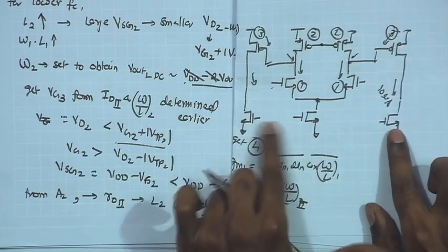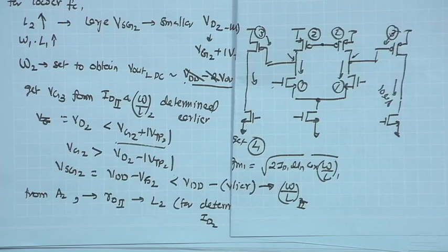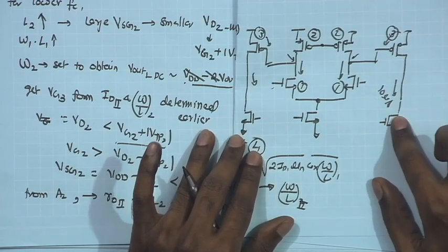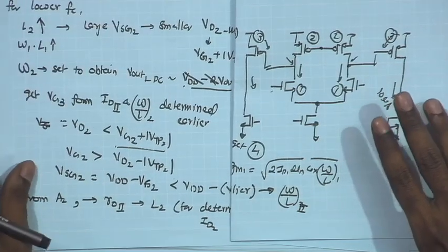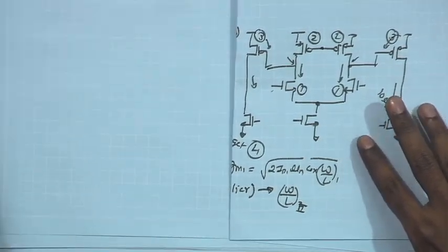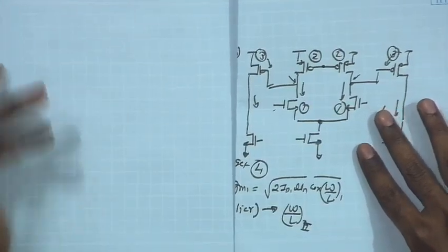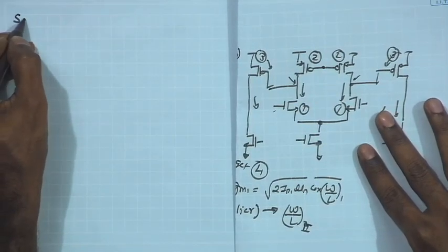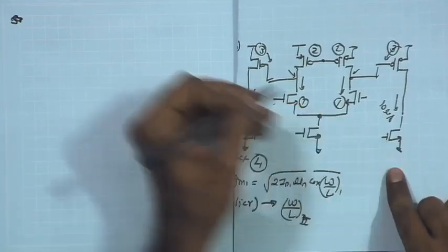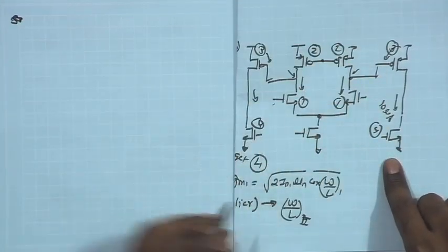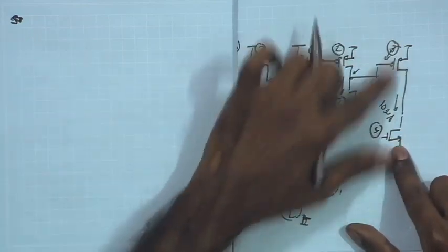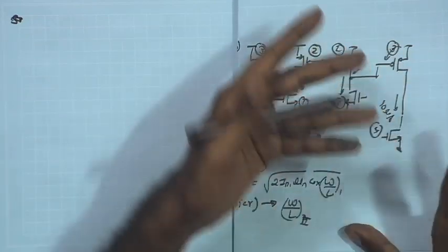Now, the next is the question of these NMOS devices. So, for NMOS devices, once again the channel length should be similar for the second stage. If I look at the second stage, if I call this M4 pair, that means I am calling these two as M4. So, once again the RO is determined for a gain requirement.